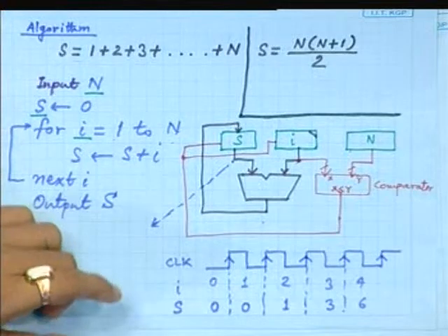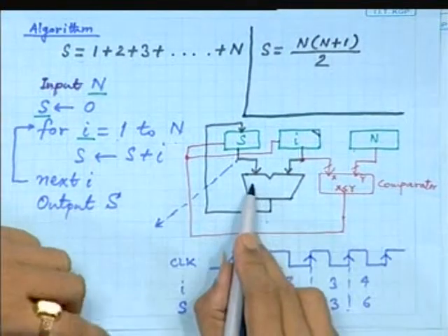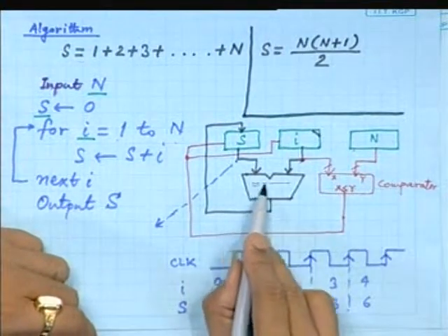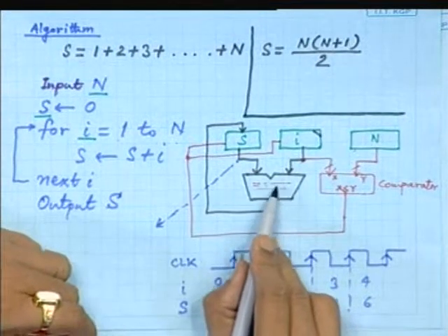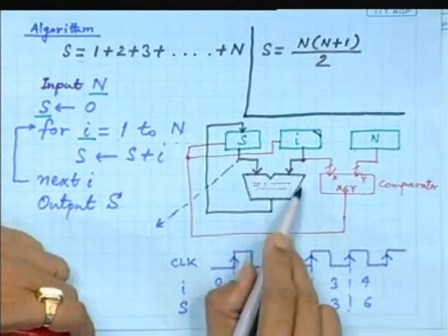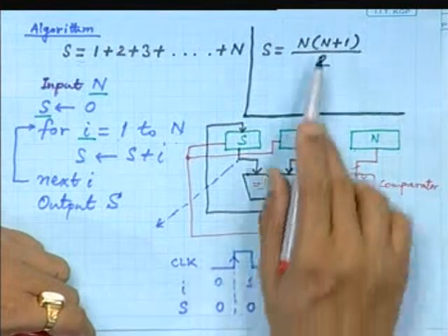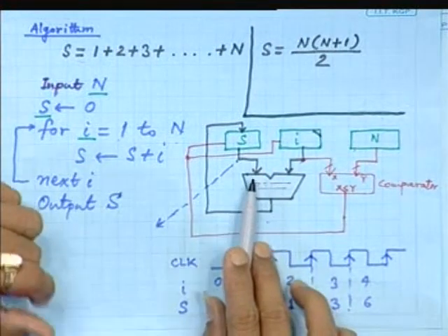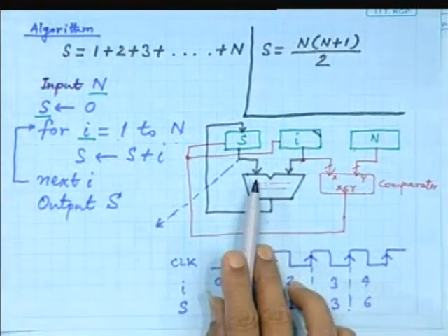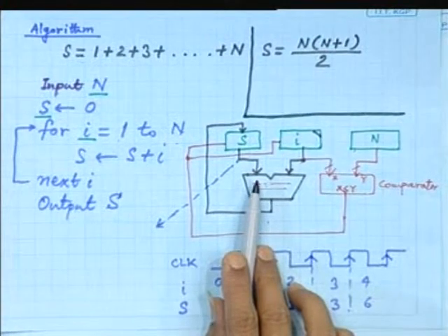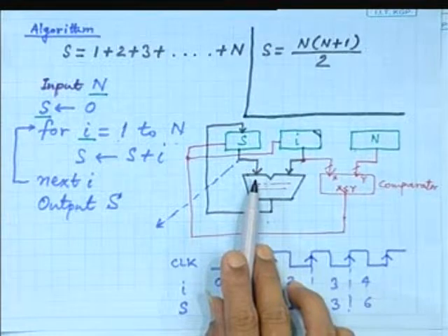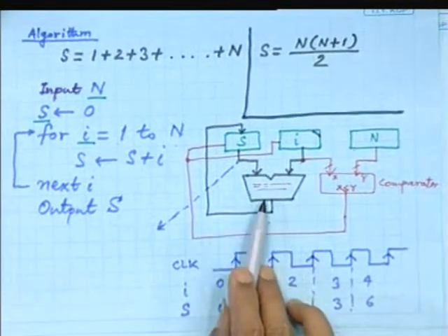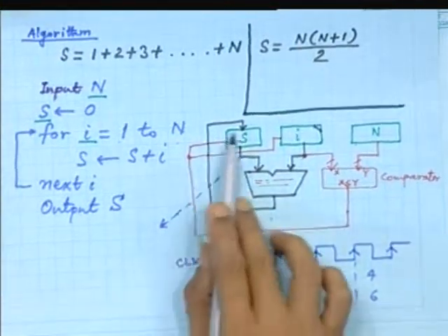Now depending on the actual internal circuit inside this, I think some of you are already aware that XOR gates, AND gates, OR gates are used here to realize this adder functionality. So they have some propagation delay. It is not that if you allow the input to change instantaneously the output will change. It will take some time. So that time will decide the maximum speed of this.